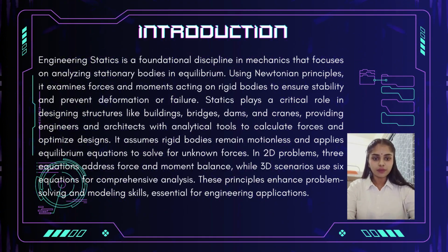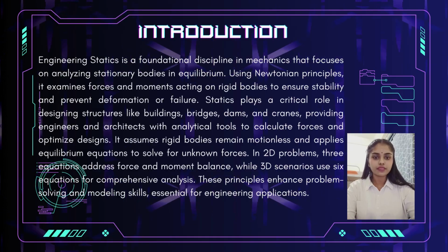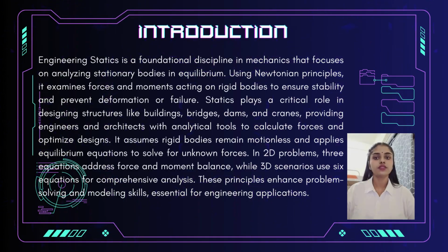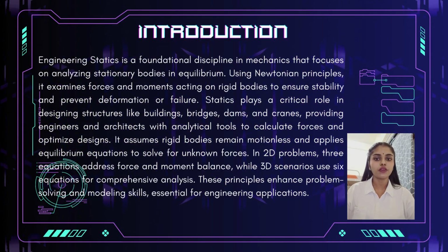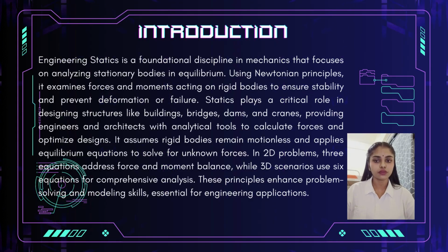In a 2D system, forces and moments are represented as vectors. To solve the equilibrium equations, we decompose these vectors into scalar components. Summation of forces in the x direction equals 0. Summation of forces in the y direction equals 0. Summation of moments about the z-axis equals 0.